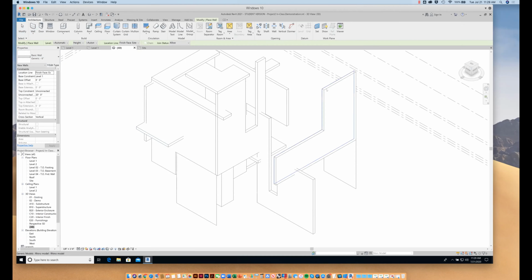I'm going to say wall by face. Now I'm going to go through one of these thickened things. I'm just going to try to select the outside faces of it. Make each one a 6-inch wall. The outside face, inside faces. Okay, I'm just going to try to go around. Because what we're going to do is make each of the surfaces around this a wall. And then we can start to add the reveal patterns around it three-dimensionally. Okay, so I can do it with that one.